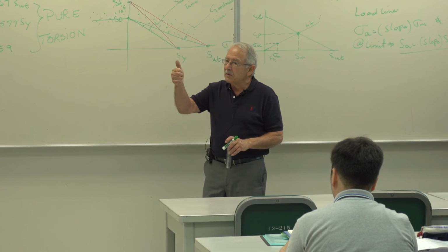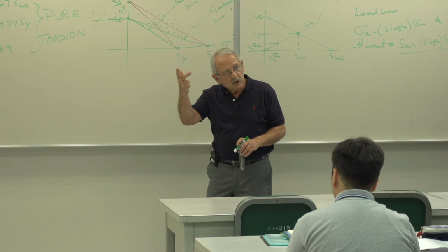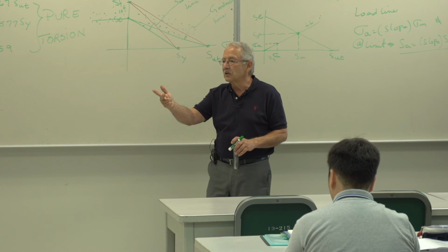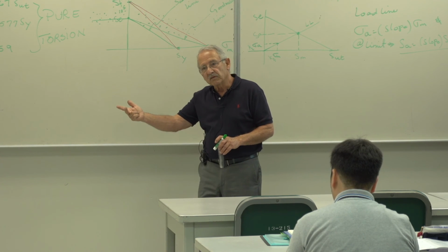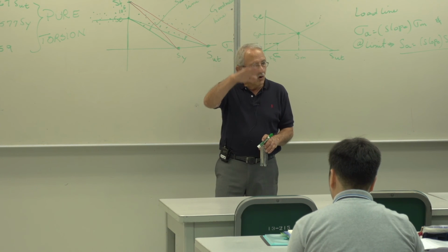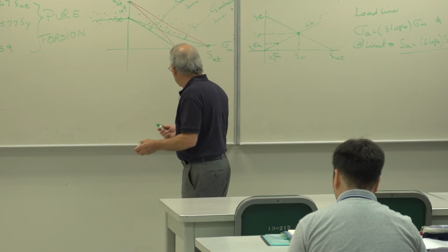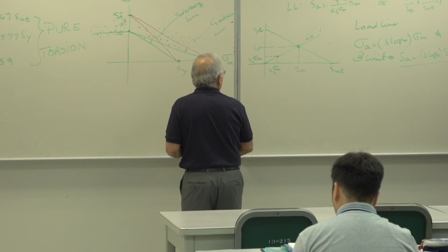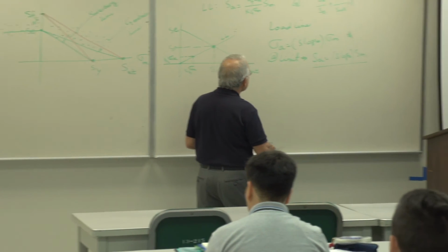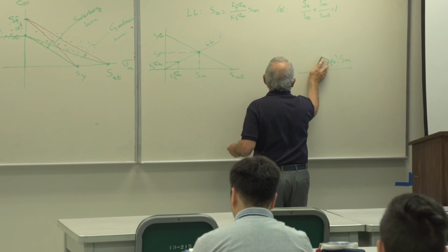Wherever the bending load is maximum, the torsional load is maximum at that time, the axial load is maximum at that time. Whenever they are minimum, they're all minimum together, and they go up and down in exactly the same manner. An example of it would be this type of loading.